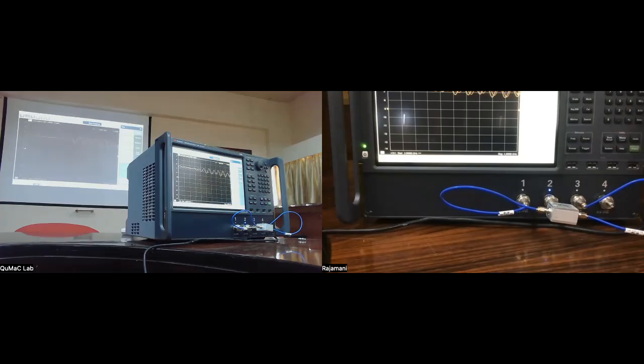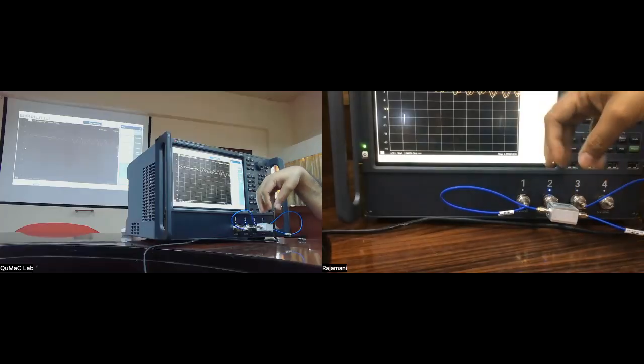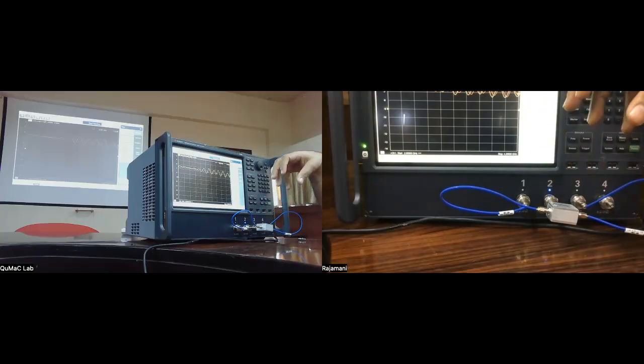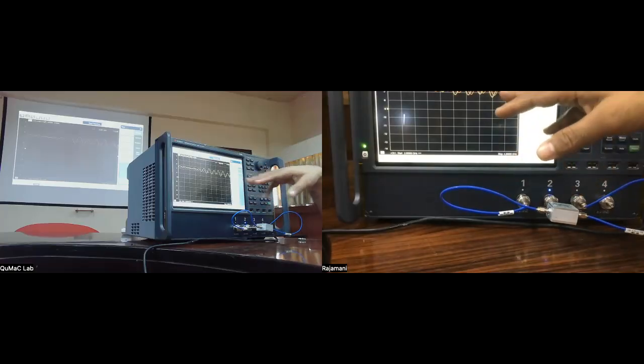Is there a particular reason why it's so flat? Yes, because it is easier to make a resistor have the same response, right? In fact, I have not shown you the circuit for this. Maybe in the next class, when we study the splitters, I will show you. It's just a resistive network divider, and it's a lot easier to make them have a flat frequency response. However, it's not so easy to make them flat over arbitrarily large frequencies. That's why this particular device is a low cost version of these things. Up to 4.2 gigahertz, it looks fine.